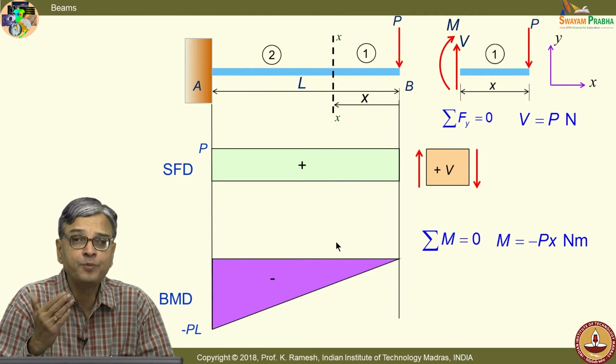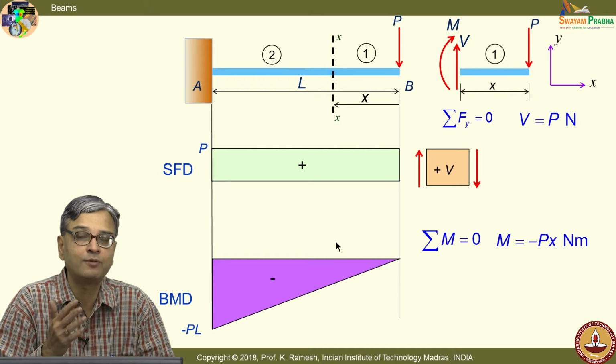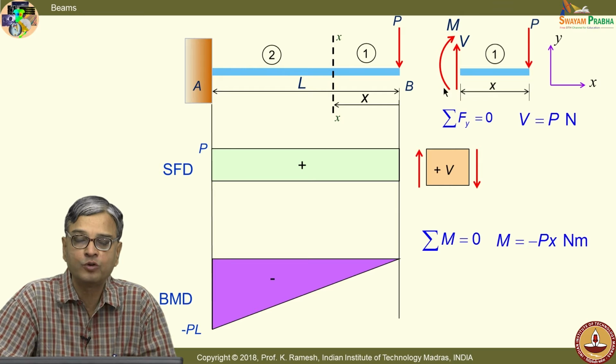It would help you to find out if you have done any glaring calculation mistakes, either in terms of magnitude or in terms of sign. I would recommend you to plan your answer scripts, and also while you take down the notes, find out a different space for doing the computations, and reserve the space below the loading diagram for drawing SFD and BMD.